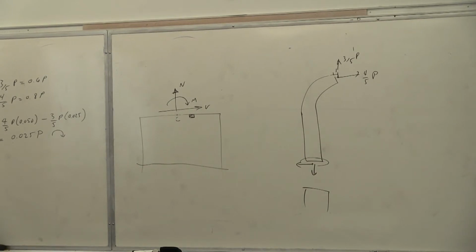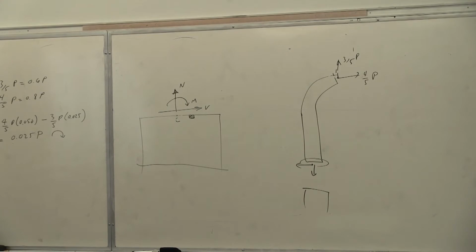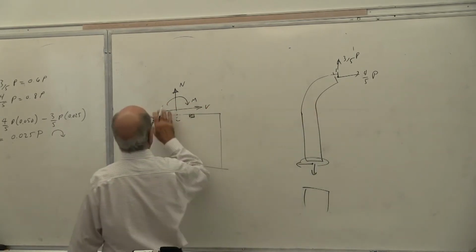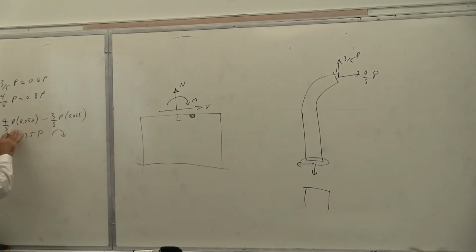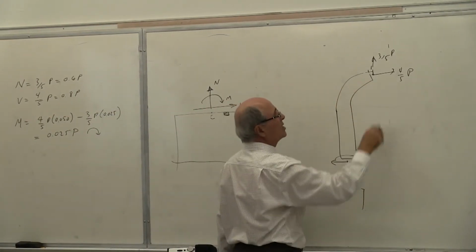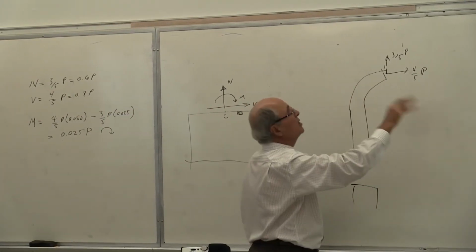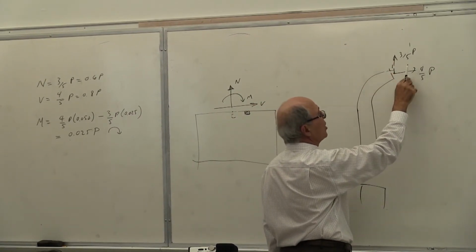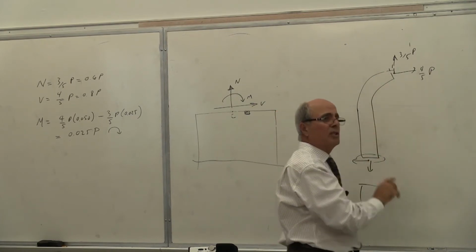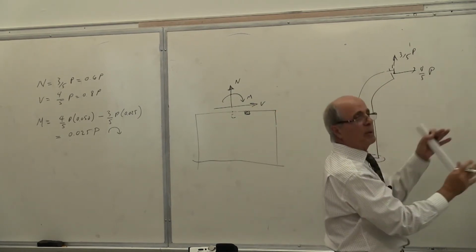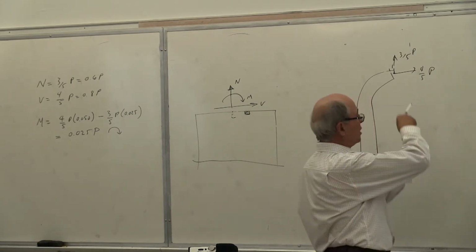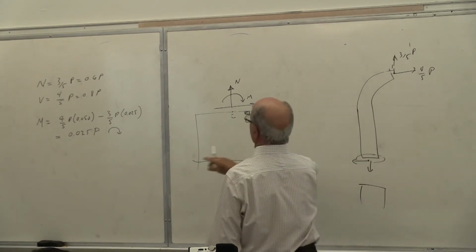If you have a problem there, whatever you put afterward is not going to work. Is that correct or not? That's why I was a little bit surprised, a little bit shocked. But nevertheless, this is the statics of the problem. In this direction, you have this much moment because notice this one is a larger distance and larger force. So obviously this moment is larger than that moment. Yes or no? This is the shortest distance, smaller force. This is a larger distance, a larger force. Therefore, this item bends this way, not this way. Is that correct? Everybody agree? Because this way the action is larger. And that's that action. So I showed it in that way.